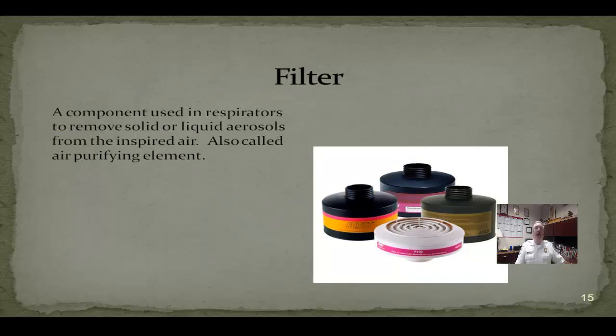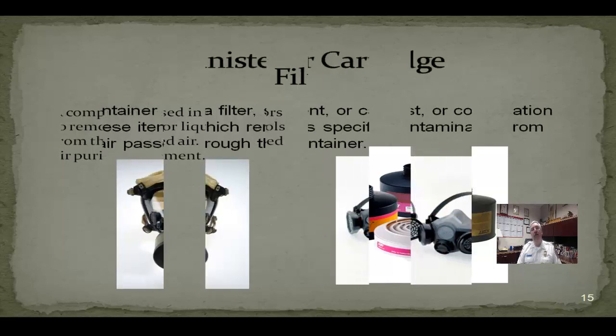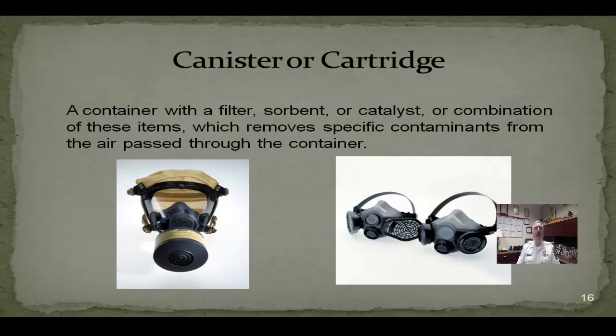The filter materials are designed to capture certain sizes and certain types of particulate matter. You've got to make sure that when we're looking at this, that we're using the proper canisters for the jobs. With this, either on our full face SCBA with an adapter, the half face, or the N95 masks, we've got to make sure that we're using the right one to allow air to pass through those filter systems directly to allow us to breathe.